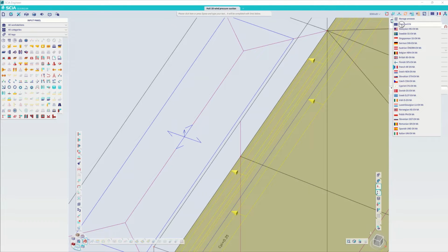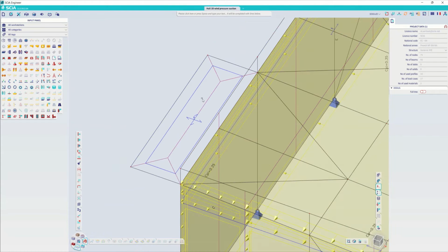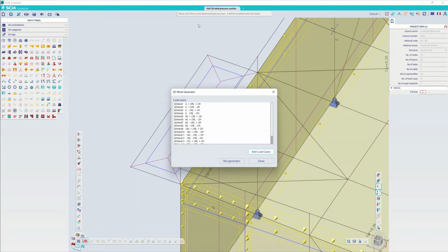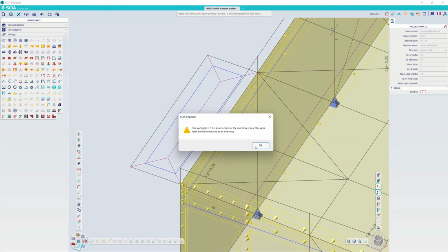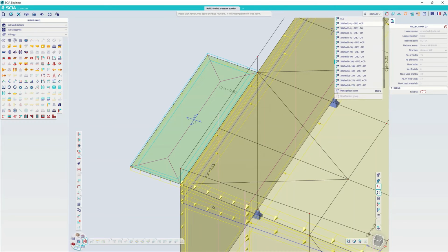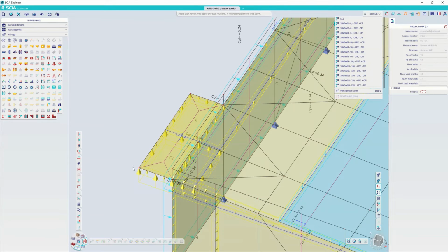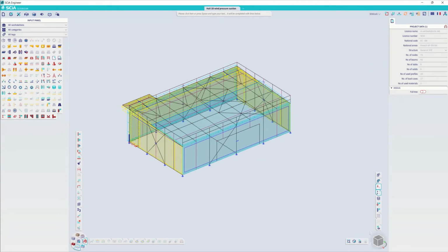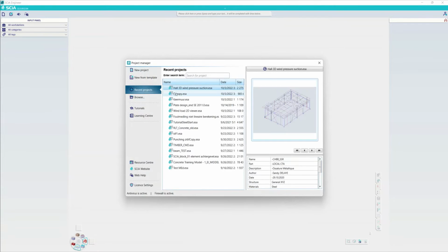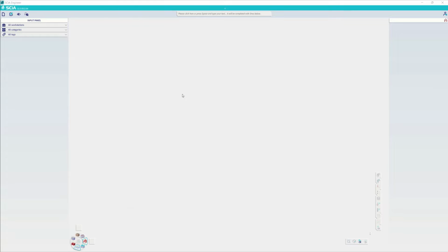on this awning. The only thing is that it's only described in the German, French, and UK standard how this load should be calculated. So whenever you use the standard approach, it will be calculated according to the German national annex. But as you can see, the loads are being generated, calculated based on the national annex you chose. And also the color of the load is related to the sign of the load, positive or negative.